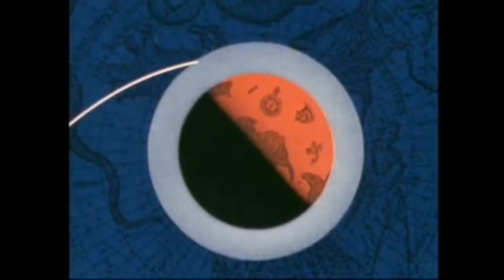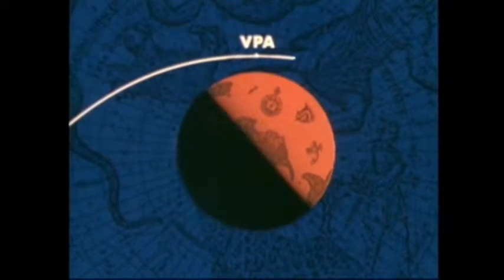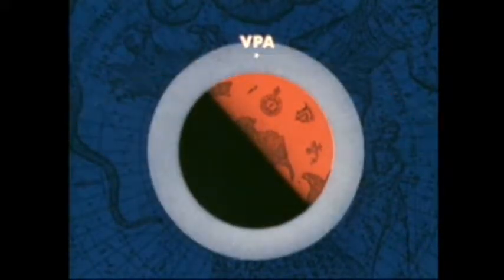This means that if we take away the atmosphere, the spacecraft would approach the Earth and arrive at a point called the vacuum perigee altitude. This would be the point of closest approach of the trans-Earth trajectory if Earth had no atmosphere. Since the velocity of the spacecraft is greater than the velocity required to achieve circular orbit, the momentum of the spacecraft would cause it to move away from the Earth after passing the point of closest approach. But Earth does have an atmosphere.